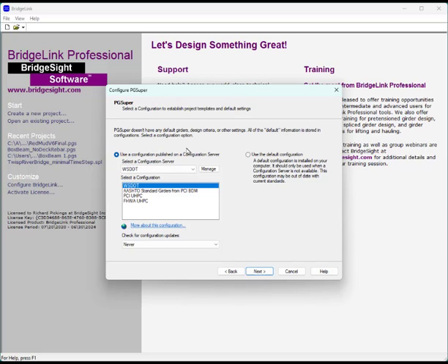As you can see right now, the program is configured to use the Washington State DOT server. On that server are several configurations, one for Washington State. And one thing of interest here is the AASHTO standard girders from PCI BDM configuration. This is a very generic AASHTO LRFD setup.